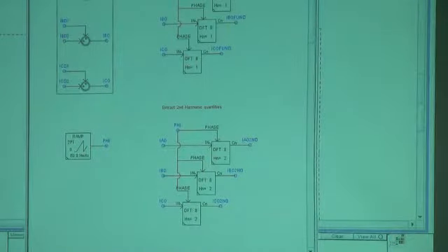So you take your sample quantities, and in this case, I'm just using a 0 to 2 pi ramp. So this changes from 0 to 2 pi at 60 hertz. Now this signal is used to tell when the DFT should sample.